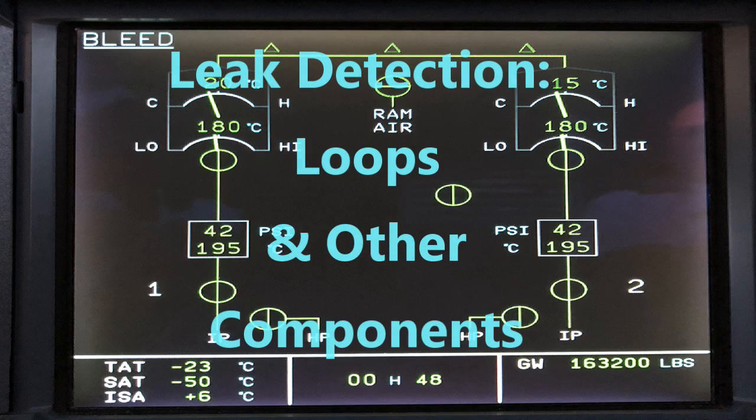Okay, so you've got those there, essentially they're sensing any overheat that's going on in those areas. Just know they're located, you see the diagram, but they're located in the APU. You've got, obviously, the engine pylons, the wings, and also the belly fairing is where they're at. They're installed in each wing.